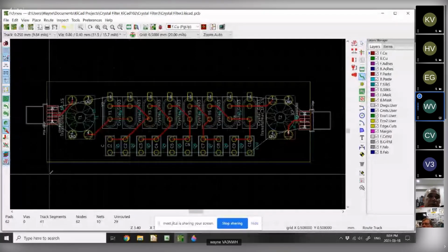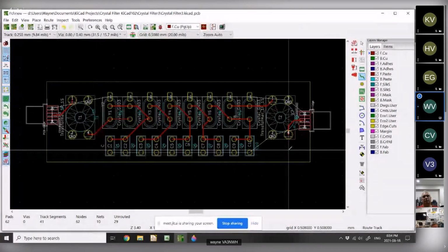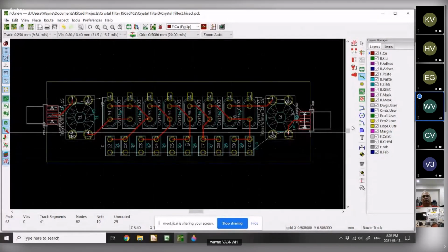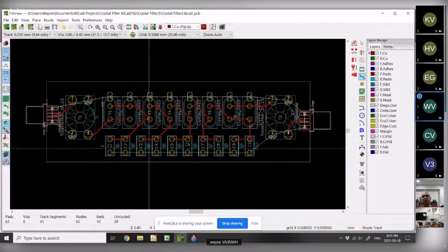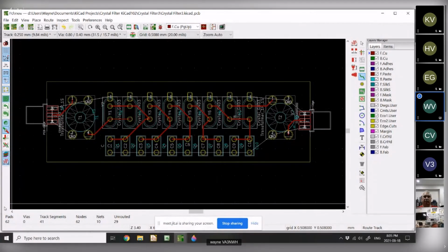So I have completed the wiring of the top layer. So the next sort of thing is there's two things you might want to do next. Those are do the grounds, of course. I can do the grounds by toggling, if I wish to, and put the grounds at the bottom by toggling and just connecting all the grounds. But I'm going to do a ground plane. Because the ground plane tends to fill in everything, I like to do a couple of other tasks first.